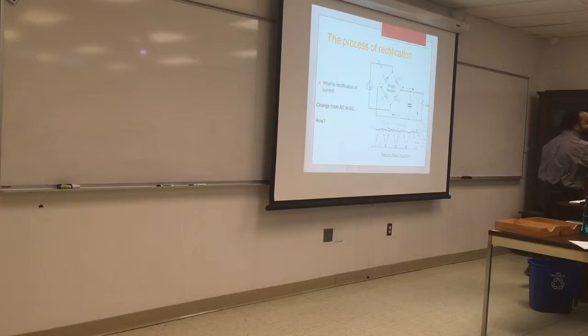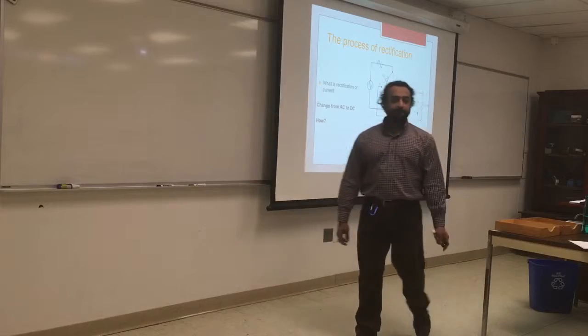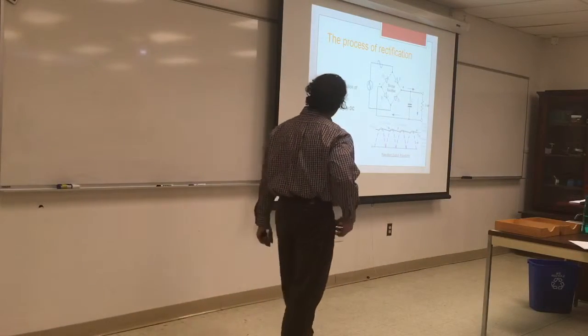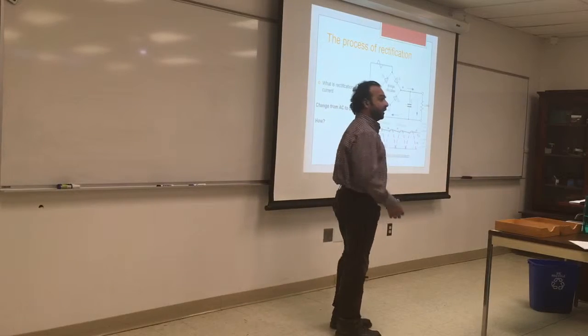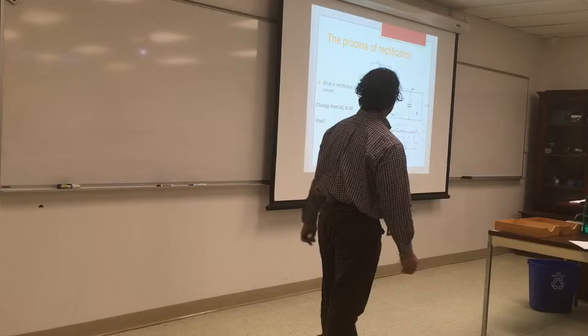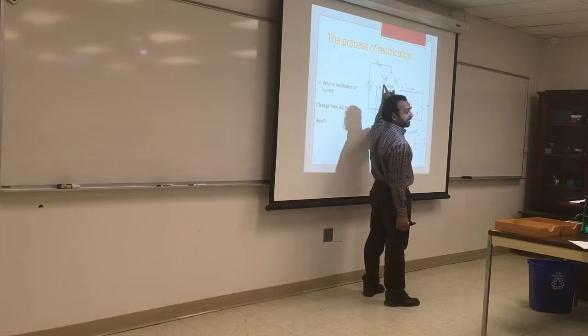So we talked about this thing which David is working on. It's called the flame rod, and I want to explain the science behind rectification. It's not something you need to know. It just will help you to know that the rectification system changes AC to DC. It does use a capacitor, and this is the symbol for diodes.